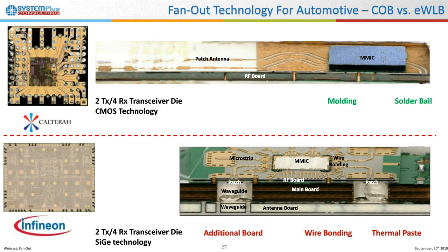So we'll begin with automotive application. Still in 2019, we have seen chip-on-board radar systems that featured MMIC devices from Infineon. Here, the choice of COB packaging is mainly linked to the antenna type. Indeed, H-pole antenna needs cavity feeding, which is already mastered by Aptiv. But for patch antenna, eWLB has been a real game changer in terms of integration.